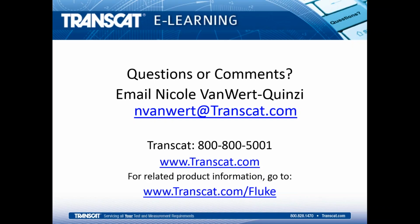Okay, for Class A or Class B RTDs, is the error tolerance linear across the range such that it can be expressed as a percentage of reading? It's just a little bit more complicated than a percentage of reading. There is an offset, but it is a linear relationship, yes. Okay, excellent.